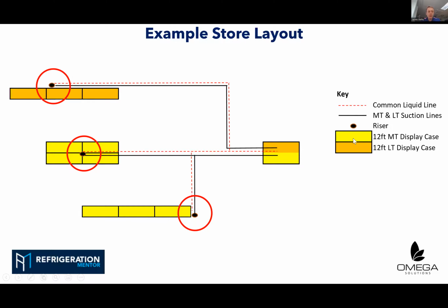So moving on a little bit, this is a real crude layout. I've effectively shown an island of 4 chilled display cases, 3 on a wall, and then behind we've got 3 low temperature cabinets. I'm just assuming that the suction and liquid lines, we've got a package plant, so we've got an onboard condenser. I've selected R448A as the refrigerant, and I'm glad I've done it this way.